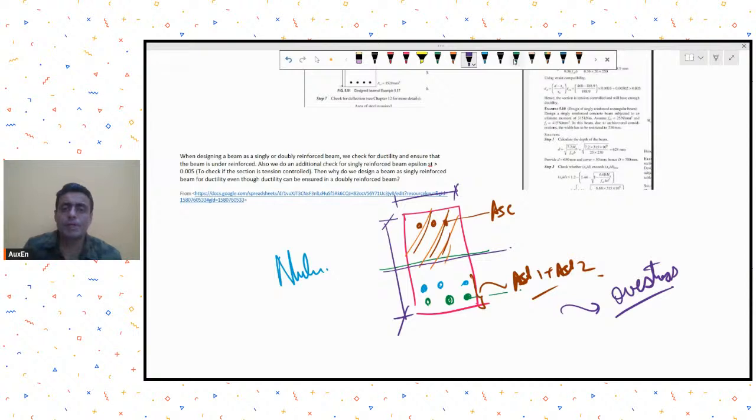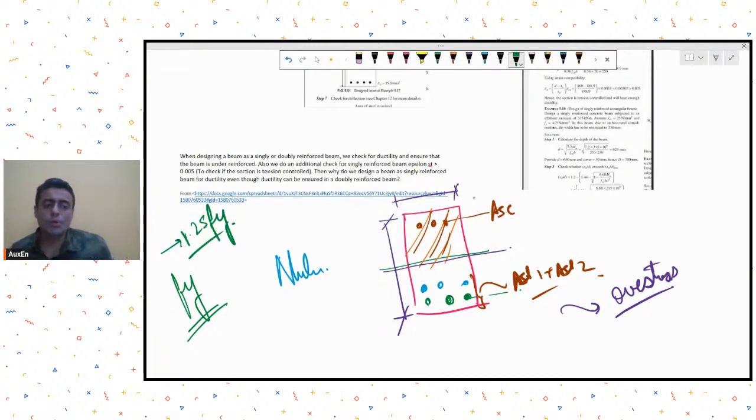Over strength factor means we were assuming that my steel will yield at Fy, and accordingly it will take some corresponding stresses, but actually the steel can take up to a higher stress value of 1.2 Fy also. Beyond Fy, that is called the post yielding behavior maybe, your steel can continue to take stresses.